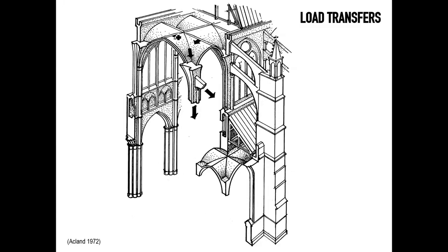So generally speaking, cathedrals can be understood, as we said, from top down. We leave for the time being the roof, which is sitting further up, and we just concentrate on these masonry vaults, normally done with small size stones. Now the vaults would discharge on the piers, as we said, using the pointed arches that define the transverse ribs and the wall ribs. And then these loads from the piers normally would be picked up by these flying buttresses that would just discharge further down towards the external buttresses.